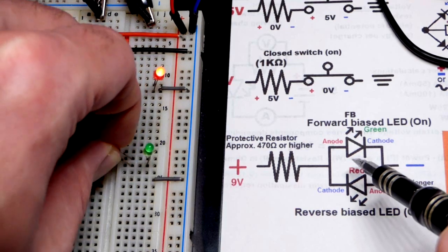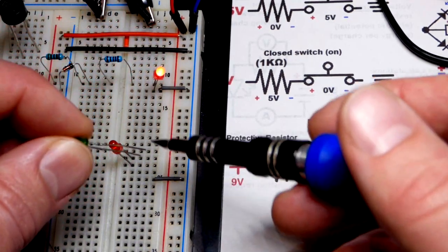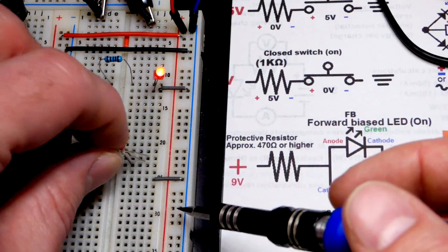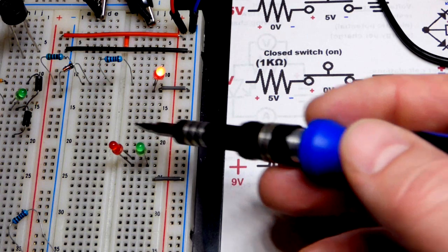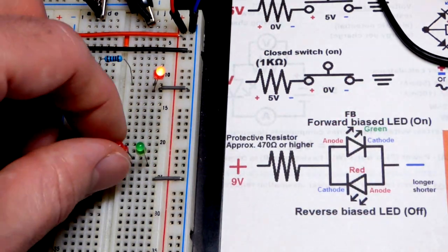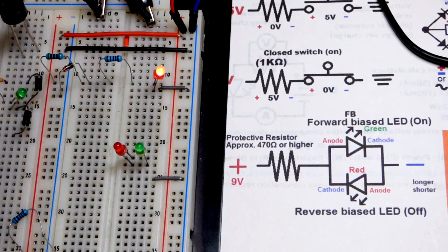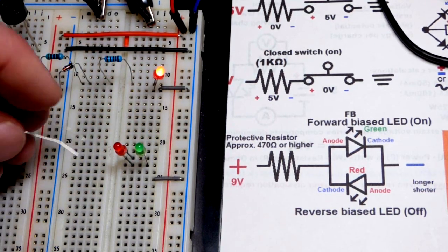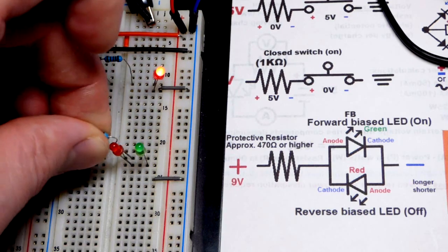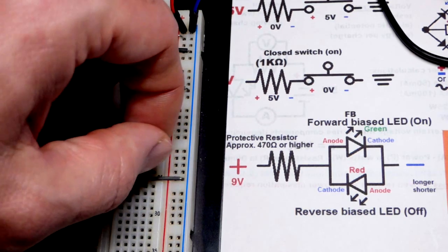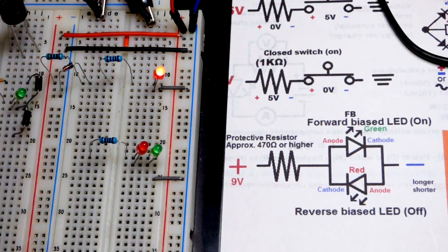We're going to do the opposite with the green LED. So the long lead, the anode, is going to be up 1 row, the short lead, the cathode, down 1 row. So the anode and cathodes are connected to each other. They're not anode to anode, they're anode to cathode. And then we will take the resistor here and put it to the top row right there, and to the top of the LEDs there. And so one's one way, the other's the other way.